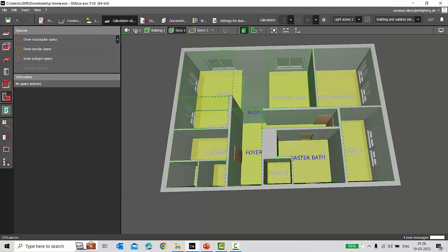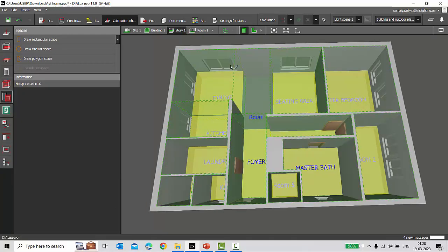And we also discussed the work plane heights. The basic thumb rule for the work plane height is to imagine what would be the height of the task area being performed. If there is any table, the standard 0.8 meters is fine. If there is no table and it is majorly used for sitting and praying, you can use 0.5 meters, which is good. And if you're using the space only for walking or moving around the residence, then it can be considered at 0 level.